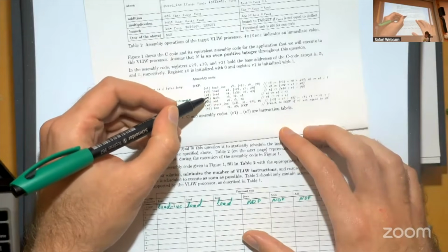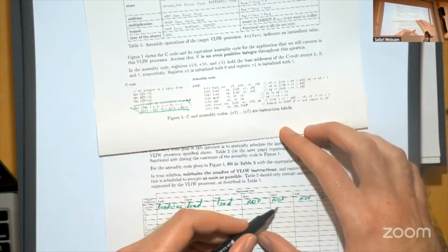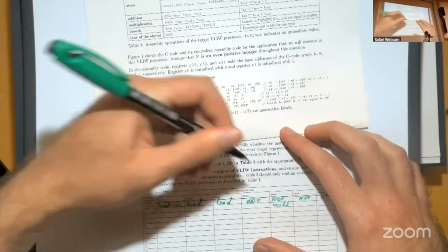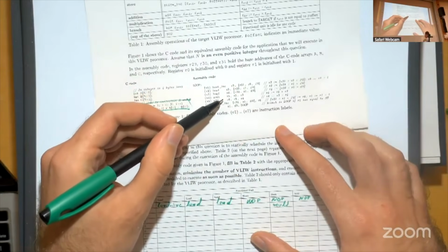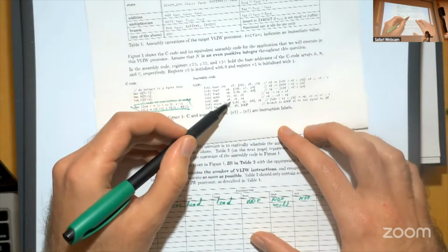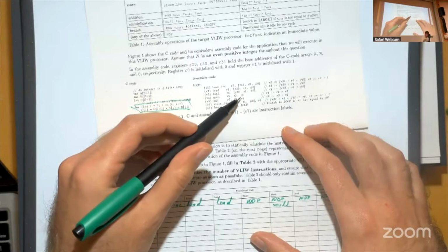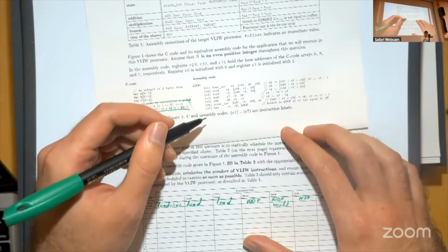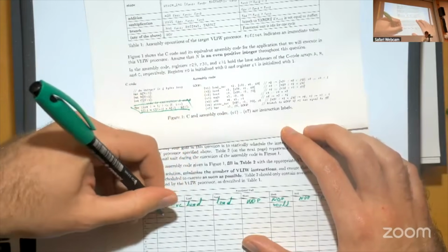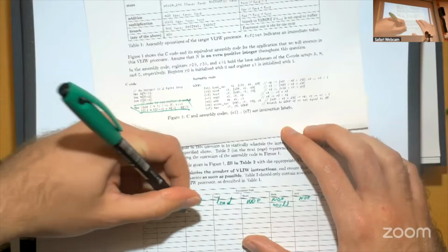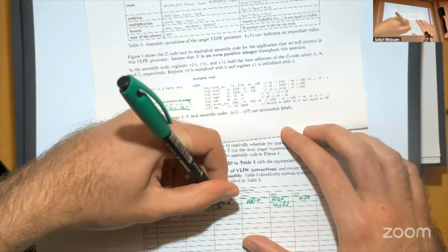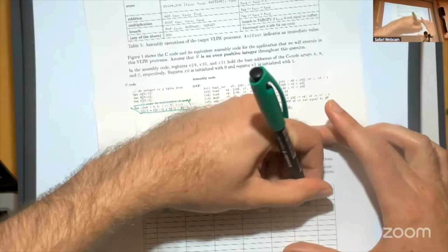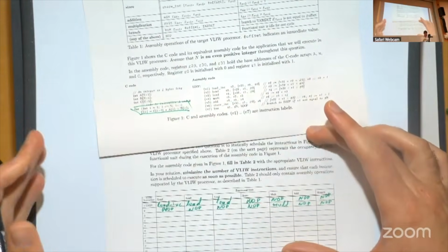So this operation goes to the multiplication unit. And the next operation depends on this. You can see it's add R6, R5, R4, and we are calculating R5 here. So this cannot be scheduled in the same cycle. So I fill everything else with NOPs over here.